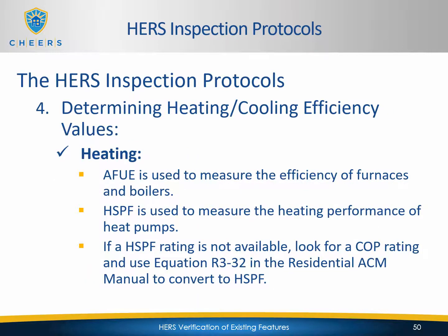AFUE is used to measure the efficiency of furnaces and boilers. HSPF is used to measure the heating performance of heat pumps. If an HSPF rating is not available, look for a COP rating and use equation R3-32 in the residential ACM manual to convert it to HSPF.